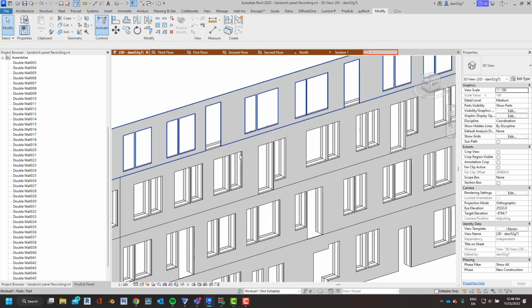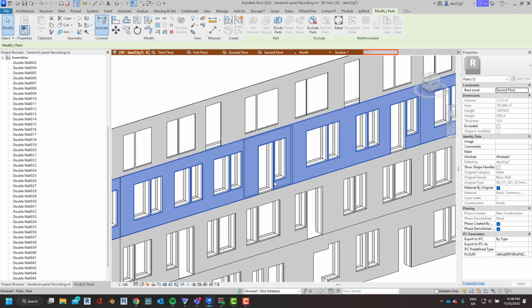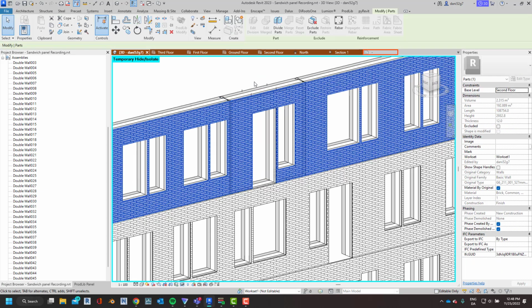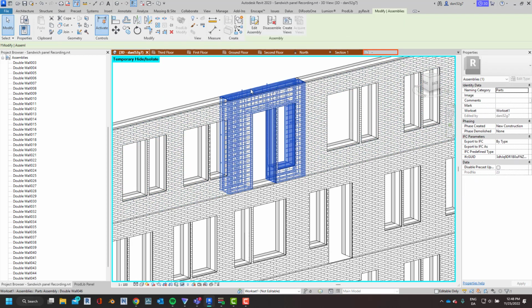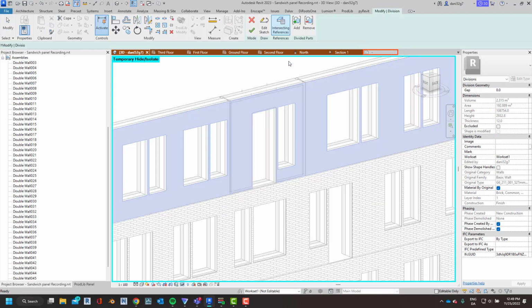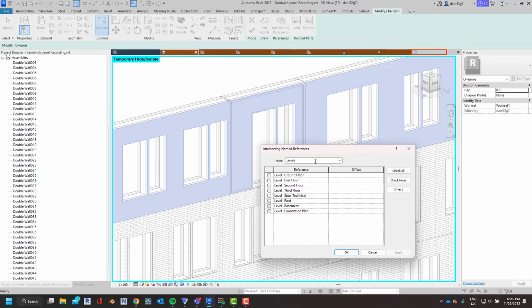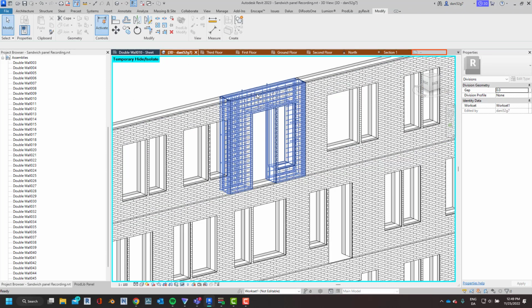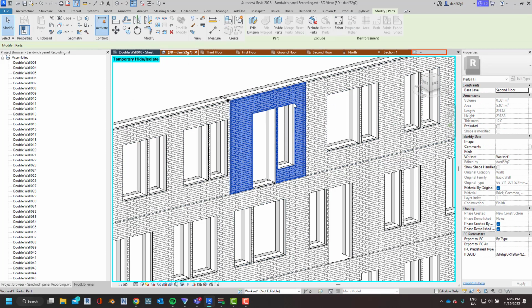So, we've loaded the brick type in. We've shown parts. We're going to hide this one. You can see now here that the assembly still exists, and now we have bricks. The only problem is now the brick part isn't split. So again, we have to just divide the part, intersecting, references, all, apply, done. Now our bricks have their own shape handles.